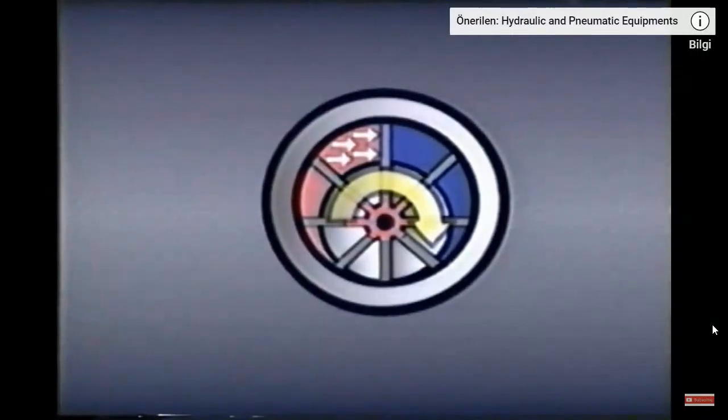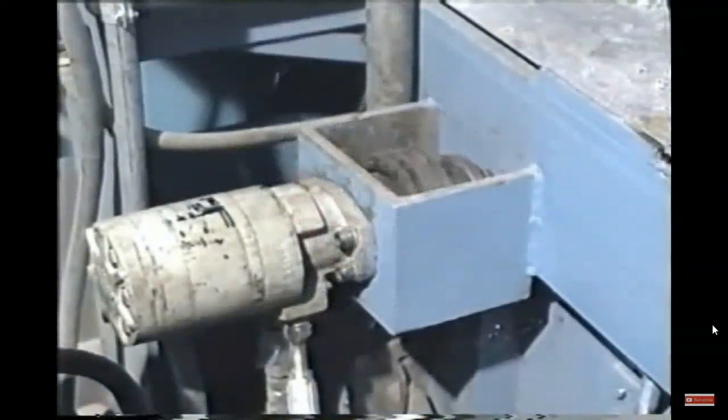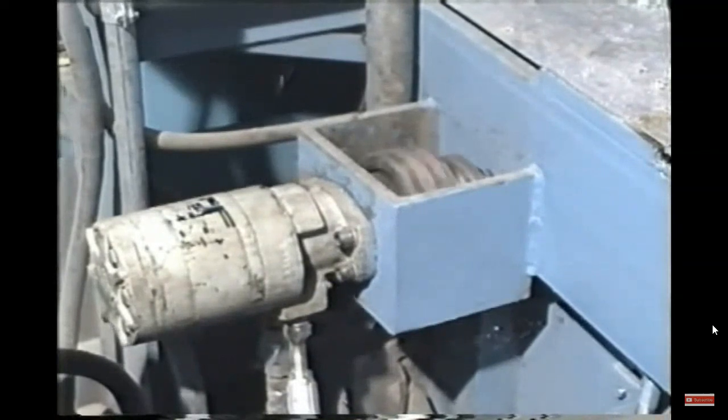As system pressure rises, the force applied to the vane increases, and the rotary force developed at the shaft, the torque, also increases. As long as the size of the motor remains the same, increasing the pressure will increase the torque. If pressure drops, torque drops. A similar relationship exists between flow rate and speed. If flow through the motor increases, then the vanes will turn faster, and the speed of the shaft will increase.